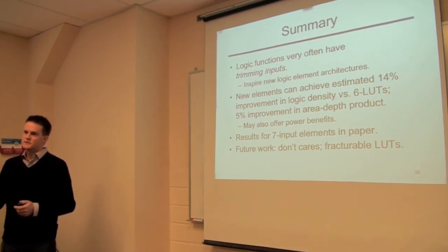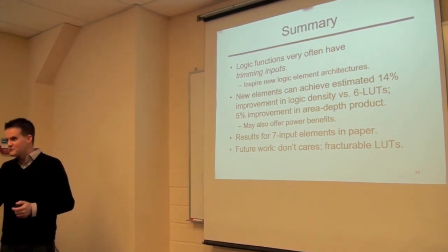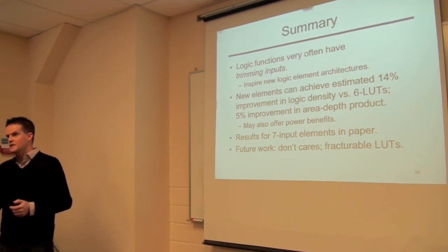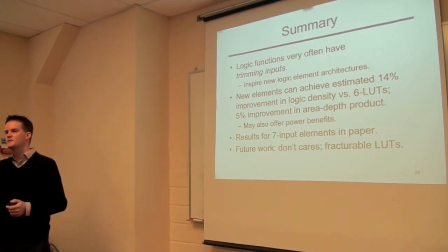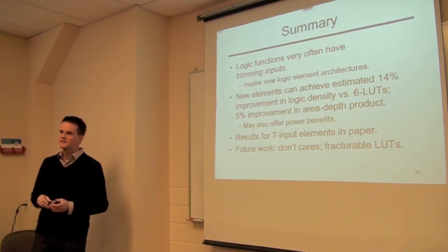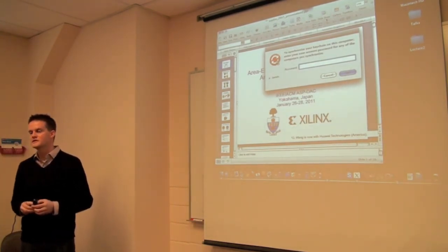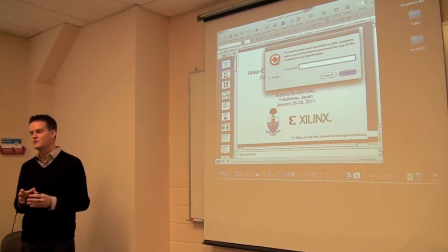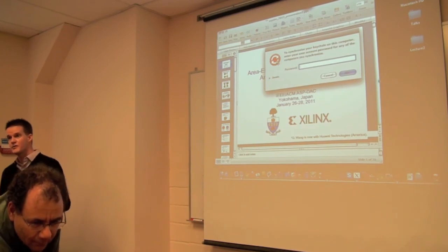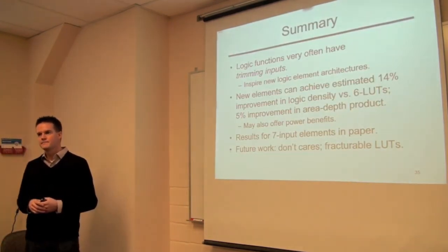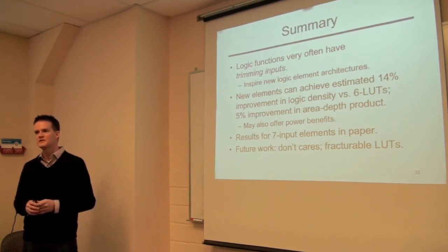So basically, when you're choosing one, you have to take one signal, let's say has a trimming input, and put it to a particular input to your logic element. Even in a standard 6 LUT architecture, you still had to route that signal to the logic element, but you might be locked to a specific pin. Now, if getting to that pin cost you more routing area, like what Jason was asking, if you had to take a roundabout path in the routing to get to that pin, then indeed, if that was a very toggly input, that would hurt you for power. But the power impact is unclear. You should have smaller tiles, shorter wire lengths, less capacitance, which should help power. So in other words, I can't give you a for sure answer to your question. I don't know.